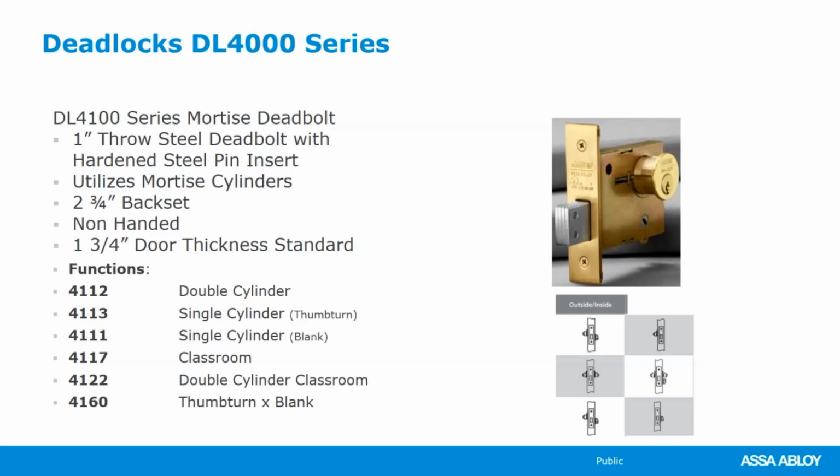However, with the cylinder on the inside, the cylinder on the inside projects and retracts that bolt as well. So we have that ability that facilities could go in there while they're working, lock the door so nobody else can come in. That's what that 22 function means. And again, there's 2 cylinders, so it has a 2 at the end. They're very, very consistent with that.